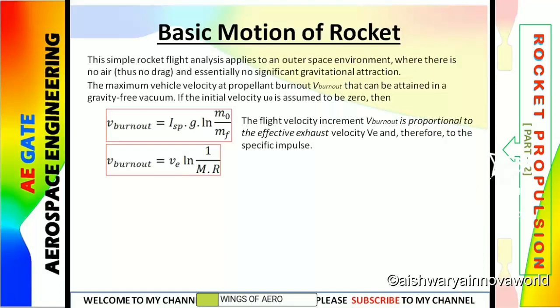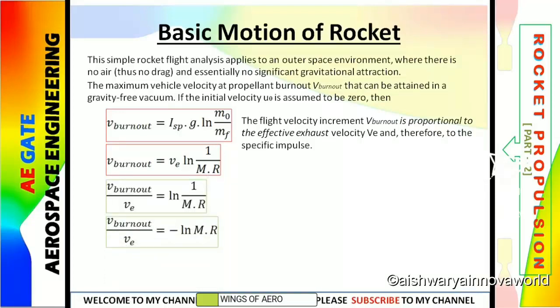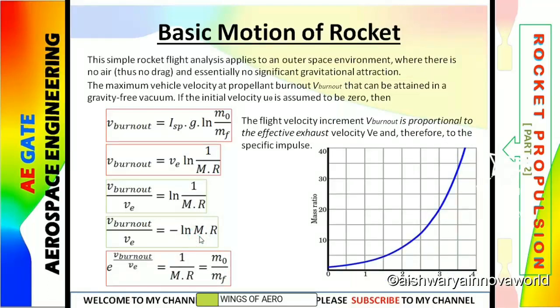specific impulse equals VE, the effective velocity, by gravity. So from here we can exchange the VE over here, and the logarithm of 1 by MR we can write as minus the logarithm of MR. Or when we need to change this logarithmic value, we can get an exponential value, and we write like this, and this is the graph.